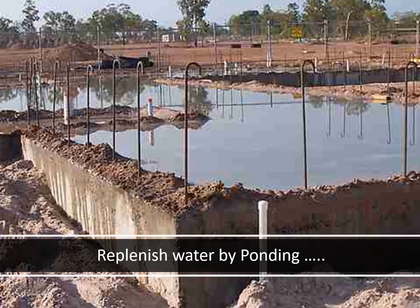Now coming to the second method, that is replenishing water by ponding. This is generally used for a base slab or roof slabs, where you can make a temporary bund and then pour water so that you have a layer of water on top of the concrete.